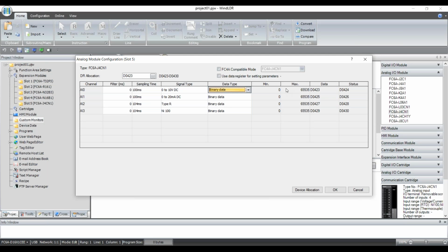And in 16 bits, you can have values ranging from 0 if all the bits are off to 65,535 if all 16 bits are on, and any combination in between. Okay. Optional range basically allows you to scale the card within these settings, and this is based on each individual channel.